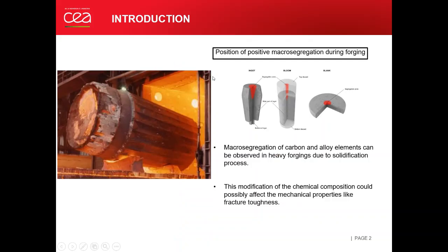As you know, in power plants, pressure vessels are made by large forging parts. Firstly, a large size ingot is manufactured by melted metal and then formed by pressure, as shown in these figures. As the solidification of the ingot starts from the outer walls, the chemical composition is not homogeneous.